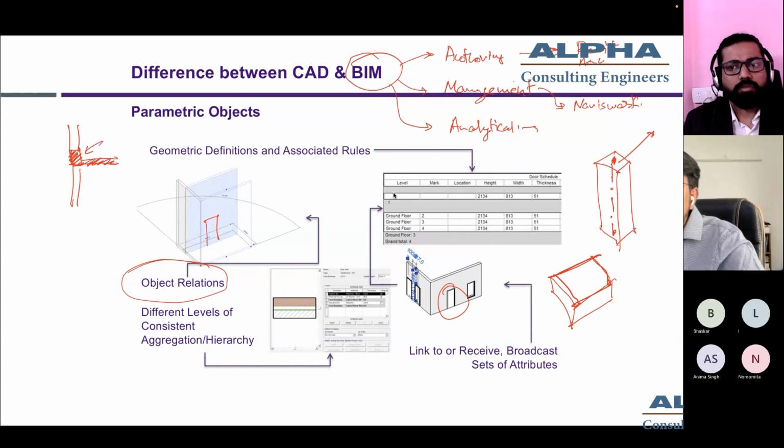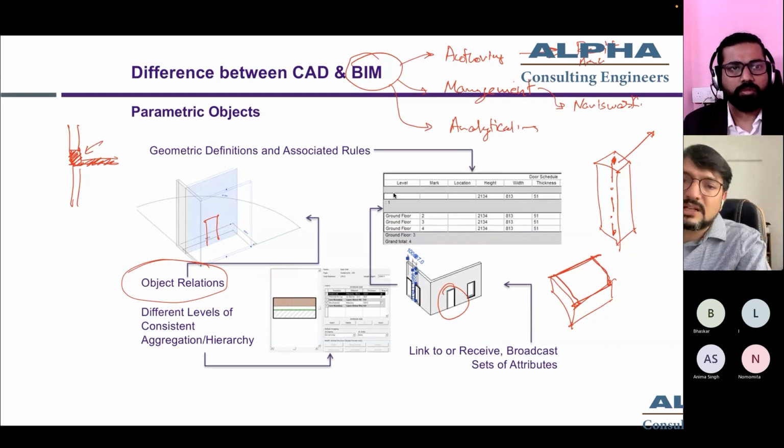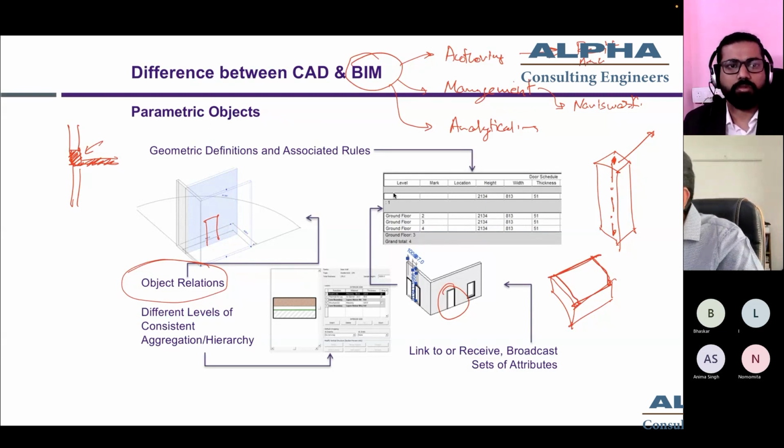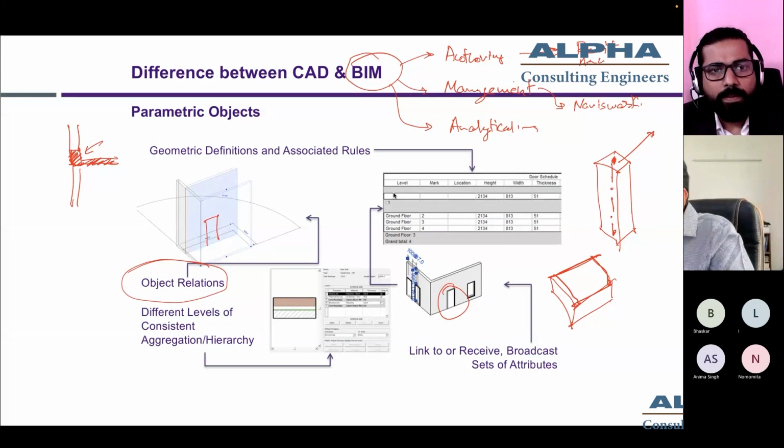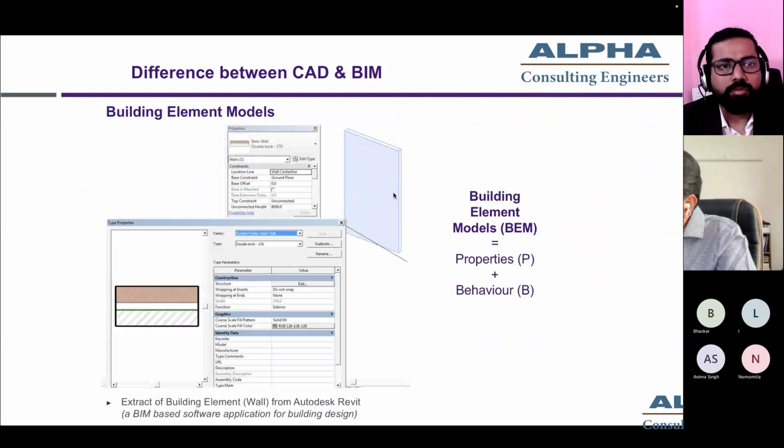You can have the connection between already existing structural analysis tools, and some arrangements, like in the case of Autodesk Revit, you have another Autodesk product called Autodesk Robot Structural Analysis. So from within Revit, you can go for the analytical detailing, analytical studies inside Robot Structural Analysis, and do the structural design there. Some advanced structural tools like Tekla, etc., are also there, which we can call BIM authoring, but discipline specific BIM authoring.